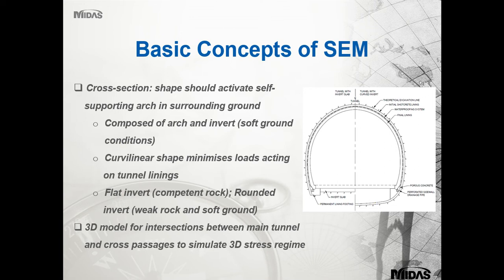Okay, the 3D model that we've created here: the reason we're doing 3D modelling for this section is that you've got the gallery connected to the tunnel itself, so it will simulate the 3D stress regime of the ground conditions on both parts of the connecting tunnel, which we'll show you in the results at the end.